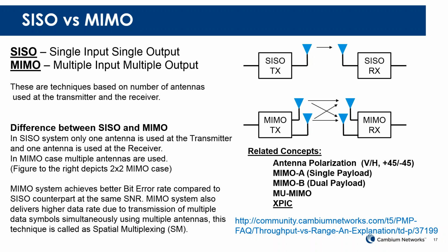It can operate in what's called MIMO A, and in that scenario the two transmitters send the same information, perhaps coded slightly differently, perhaps delayed slightly differently, sent out on two different polarizations. What is polarization? If you're familiar with Polaroid sunglasses, what do those do for you? When you put Polaroid sunglasses on, it blocks certain parts of the light so that your eyes don't get glared by the sun. In some similar fashion, that's what's happening when you polarize antennas in certain ways. One antenna may be polarized vertically, one horizontally, and what that's ultimately doing is trying to block or provide some isolation between the antennas, so that one antenna doesn't get interfered with by the other antenna that's using the same frequency.